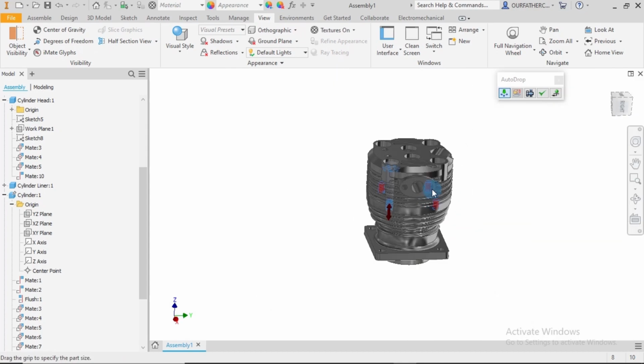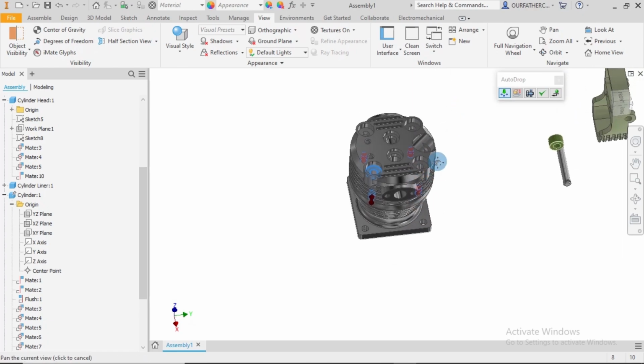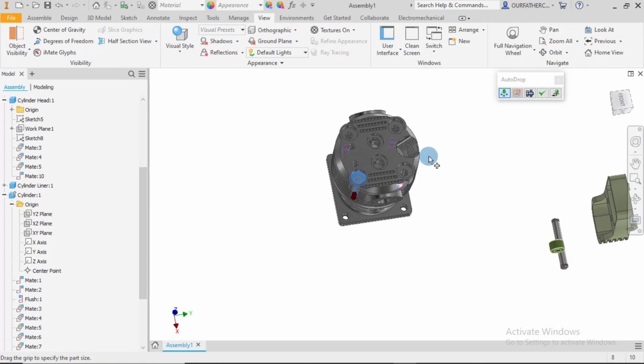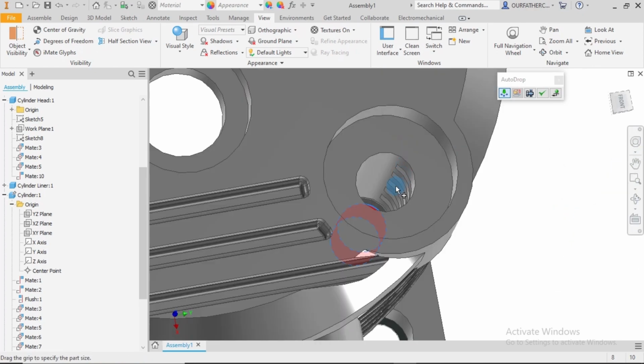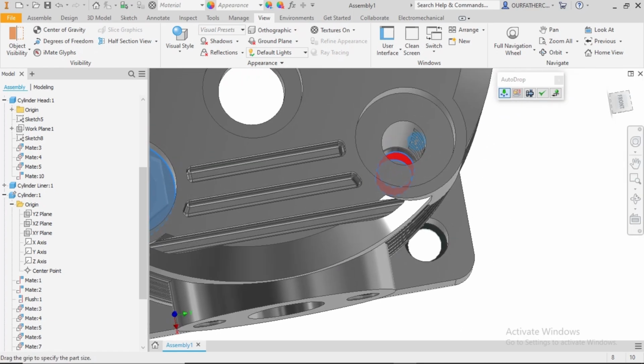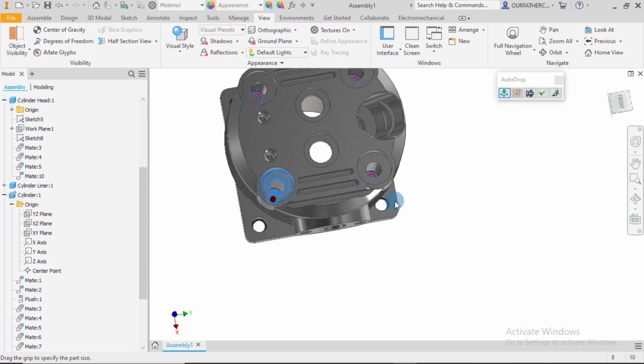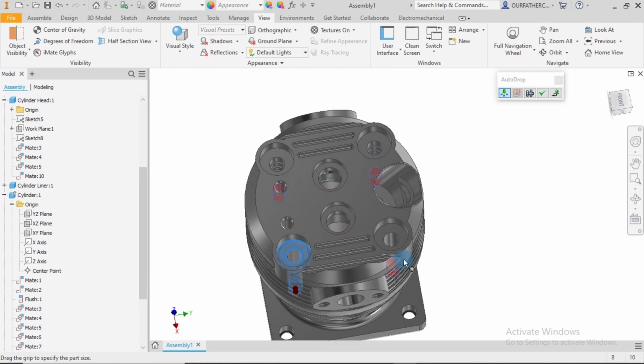Alright. So for the hole I was talking about, I'll just show you. Yeah. So you see a threaded part here. So that will be the hole you select. You select the surface itself, and then after selecting that, you select on the face to rest the bolt on. Alright, so in this case, since we have 4 identical holes, we make sure that this is checked.